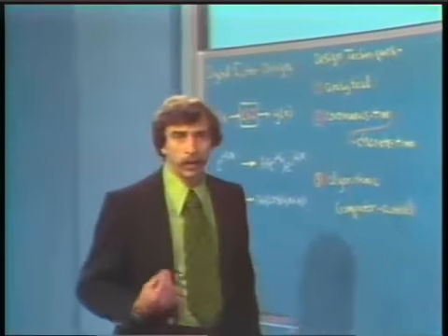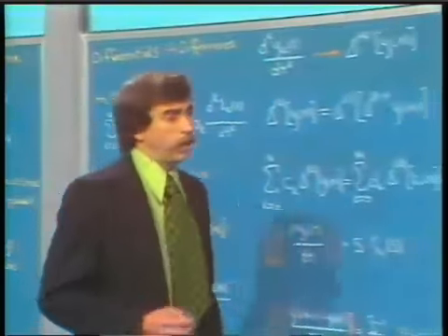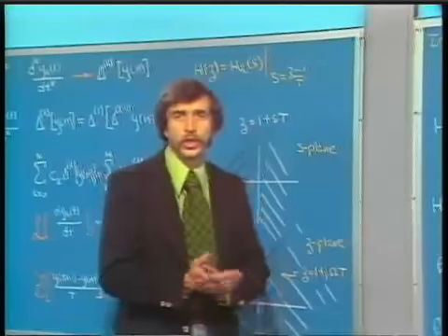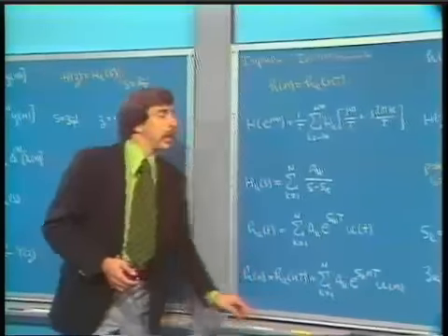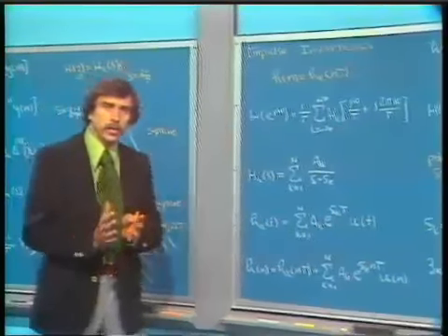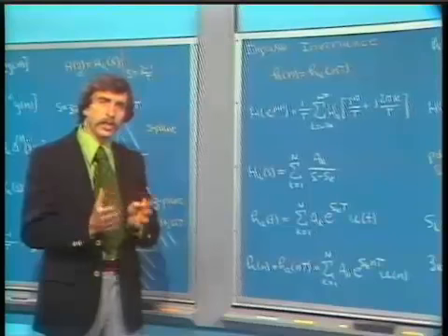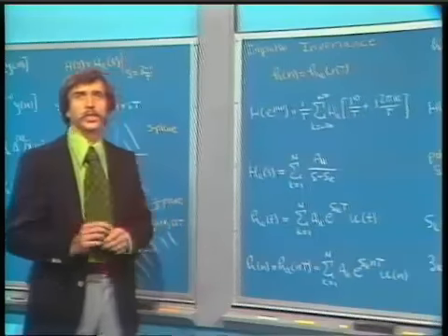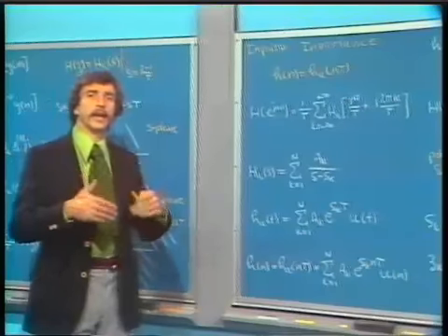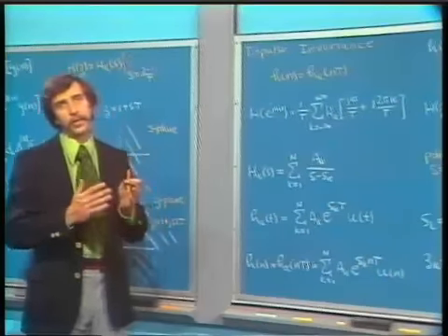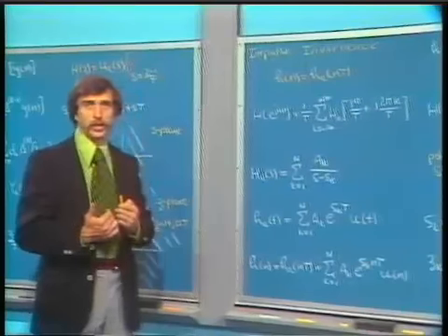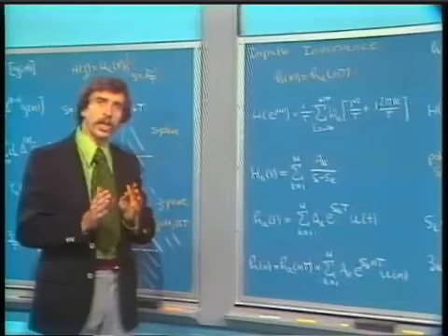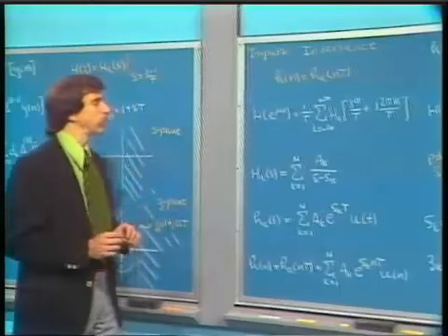with the impulse invariant method, one of the important advantages of impulse invariance is the fact that it tends to preserve good time domain characteristics, that is, the impulse response characteristics were preserved, and also it provides a linear scaling from analog frequency to digital frequency, so that if we had an analog filter with a very complicated frequency response, then we could be assured that the corresponding digital filter, except for aliasing, would have that same shape, but only with a linear scaling of the frequency axis.